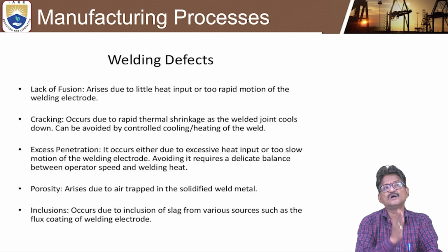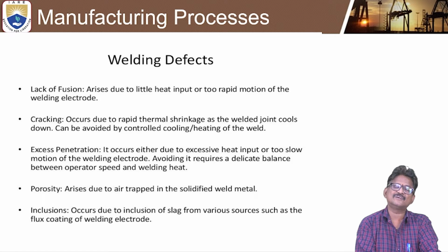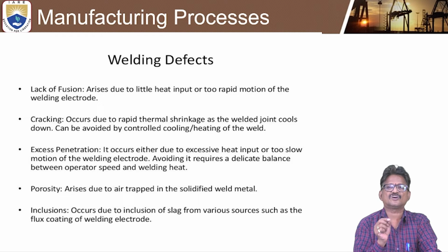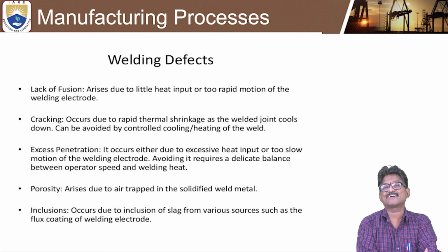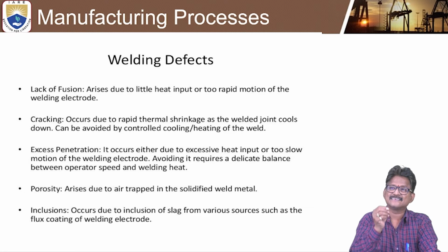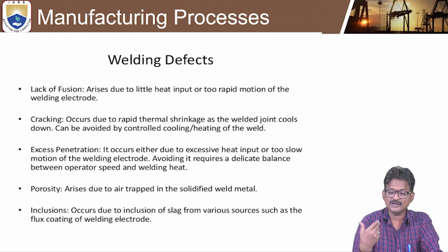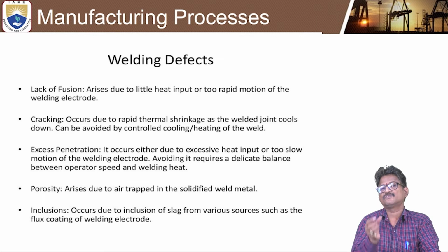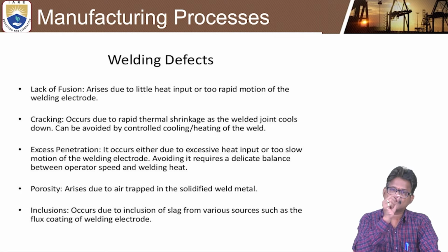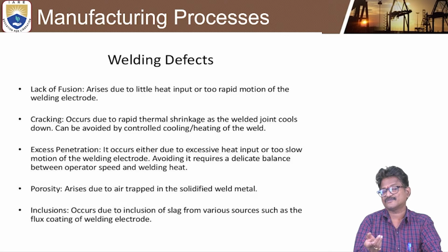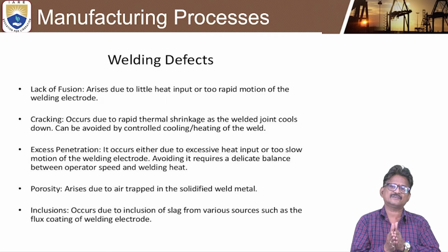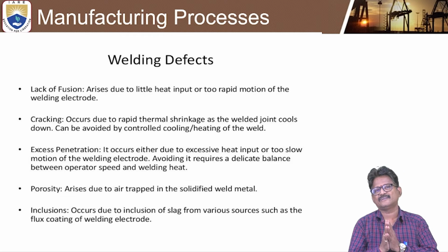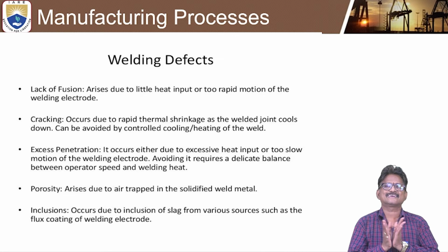You should maintain proper heating and cooling of the electrode and electrode torch. These are very important things to avoid such types of cracks. Even some line cracks and hair cracks occur, and it is very difficult to see them. When you put it under a microscope, that defect shows up. When people are asking for high quality products without cracks, we should be able to maintain the proper cooling and heating of the welder, which will affect the cracking.